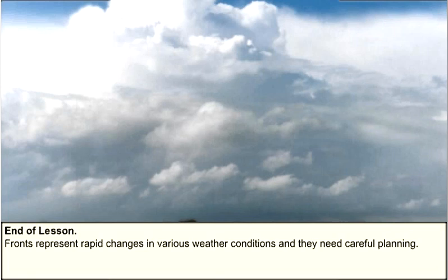The passage of fronts has significant implications for private pilots. Pressure and temperature changes can cause altimeter altitude errors of up to 1,000 feet or more. Crossing any front will inevitably lead to flying on instruments, and combined with wind changes, this could be dangerous for an inexperienced pilot, even one with an instrument rating. When fronts are present, pre-flight planning needs to be especially thorough and detailed if the fronts are to be avoided or negotiated.